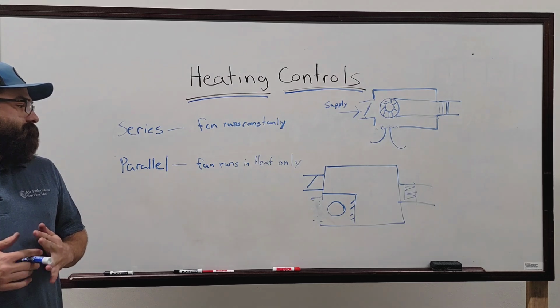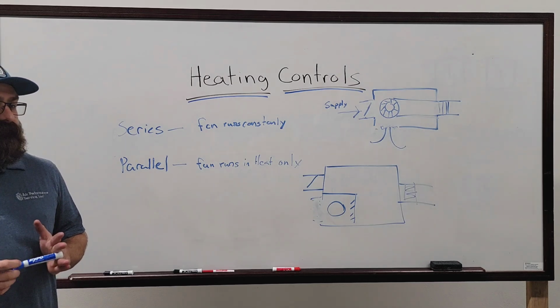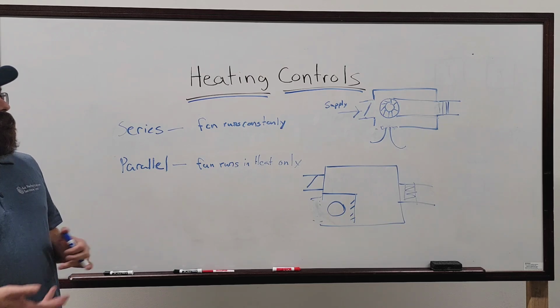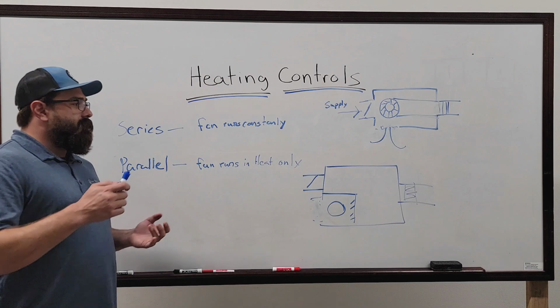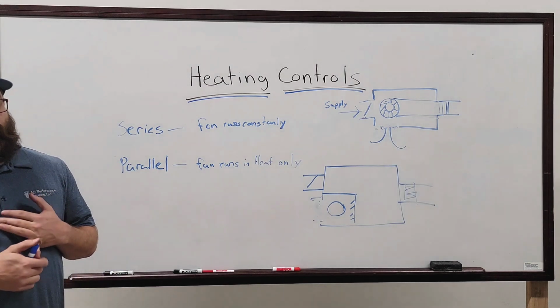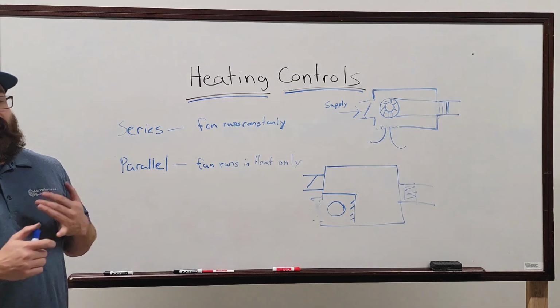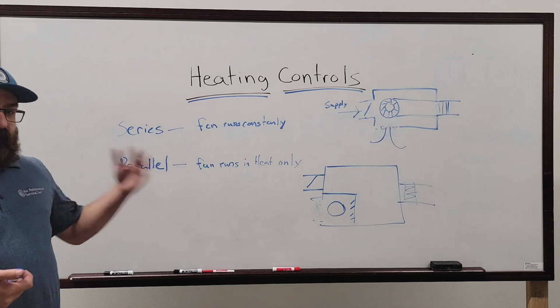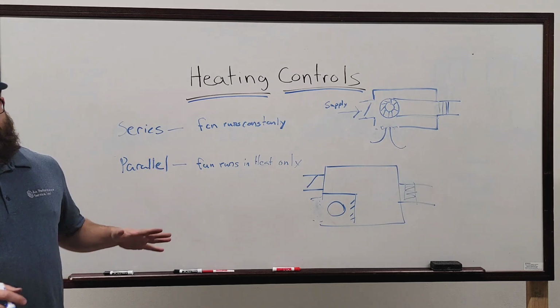So, yeah. Any other questions on VAV fan powered boxes? General rule of thumb, the way it works is your fan has to be on for heat, no matter what, because they typically have an airflow switch in them that requires positive pressure to engage the heater. So fan always has to be on for heat.